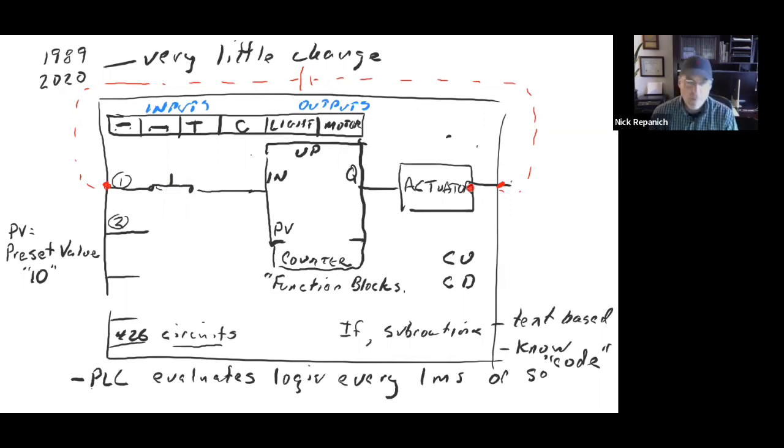Okay, easy to represent. Ladder logic is really good at this kind of stuff. And you didn't have to learn any text-based languages. Since circuits are still in existence and you still hook them up, when you're doing simple systems that are just on-off control, that take into account a number of factors, let's say you wanted to automate something at home and you didn't know code. You could go buy one of these little PLC boxes, and you could probably do this language without having to learn coding. And if you go out to the manufacturing floor, that's where we still are.